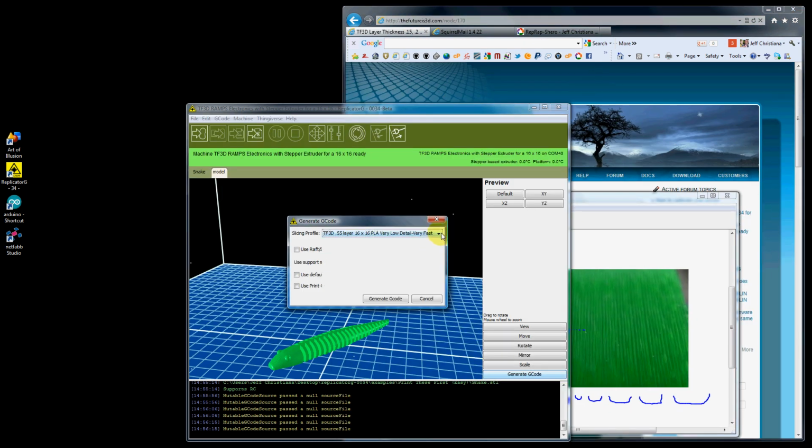We're going to have different nozzle sizes, so I'm hoping to have nozzle sizes all the way up to 1 millimeter hole, so a person could print an extremely large object on our printers, especially our 18-inch high build height printers, and do it quicker. 0.55 is about as much as I can do with a 0.35. The plastic just can't get out of this nozzle fast enough to do anything larger than 0.55.